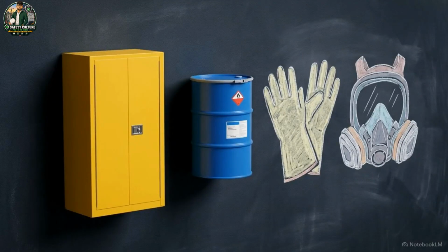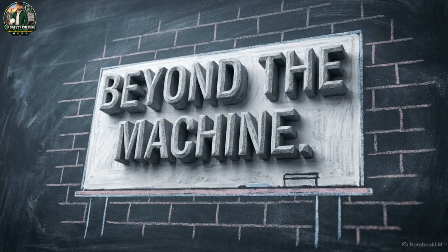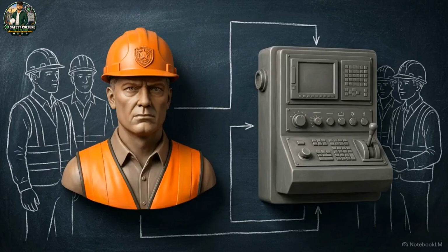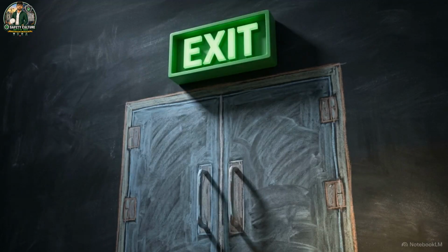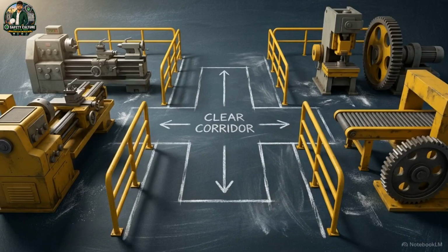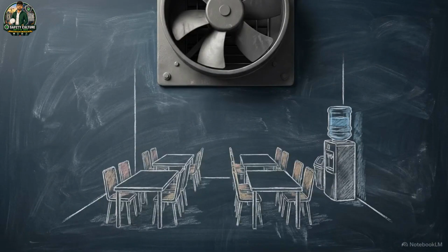The handling, storage, and internal transport of chemical substances must be conducted without exposing workers to health hazards. Third, providing safe machines is only part of the requirement. The occupier must also provide intensive safety training, clear operational instructions, and constant floor supervision. Fourth is safe transit. The physical points of entry and exit, the access and egress routes, must be maintained in a practically risk-free condition.